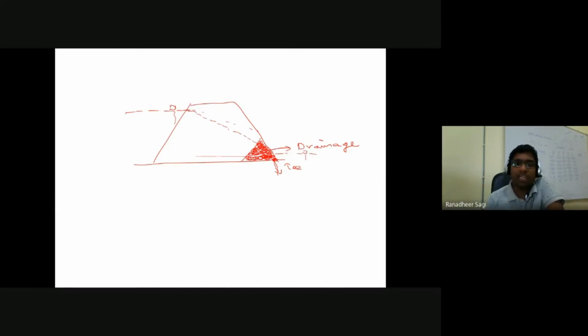In a similar way here also, if a proper drainage is provided, then all the flow lines, which represent the direction of flow through that cross section of the soil strata, will intersect with the drainage. All the seepage from upstream to downstream flows through the cross section of the embankment, and the water gets drained through the drainage and moves properly onto the downstream.